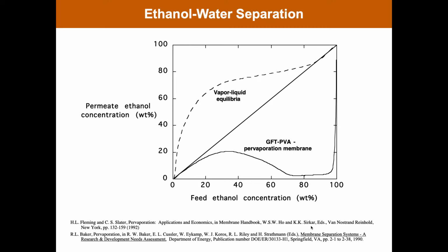It enters a distillation column that can easily take it up to about 50%. You get a lot of driving force down here, and then would often go to a second distillation column that would take it further, and that second distillation column would be pushed in terms of temperature and pressure to get as close to the azeotrope as possible.